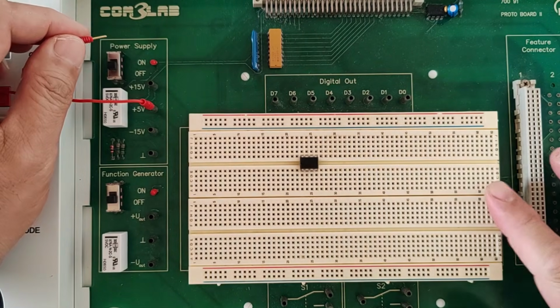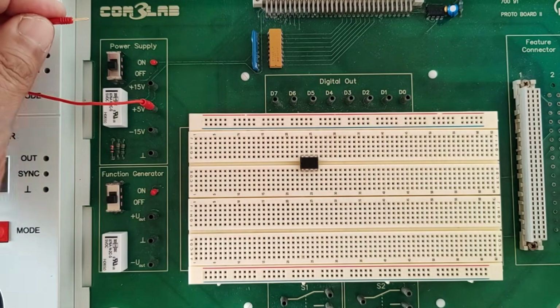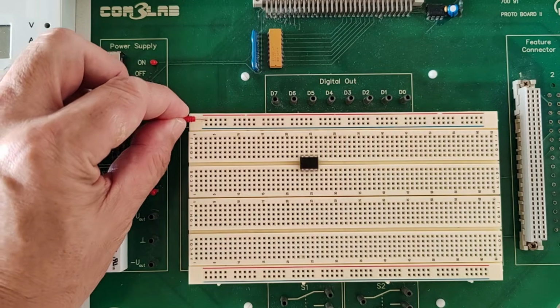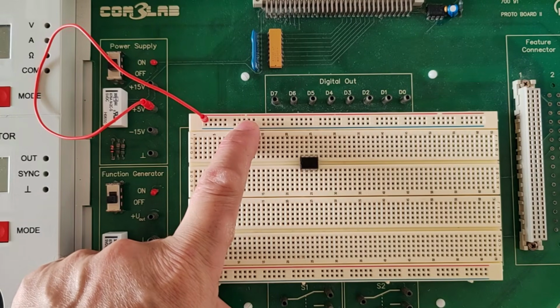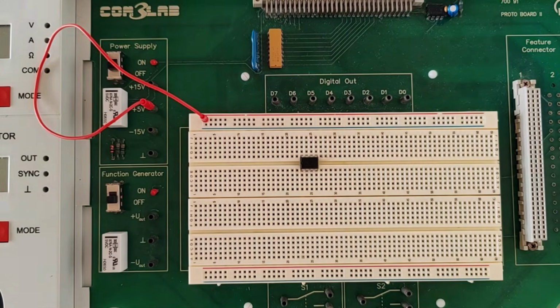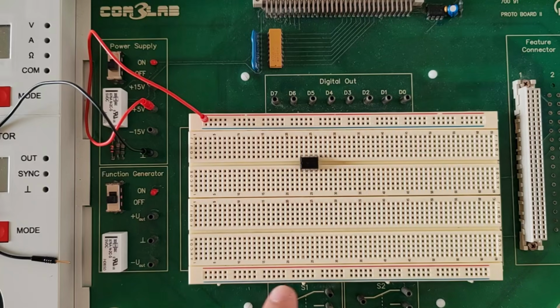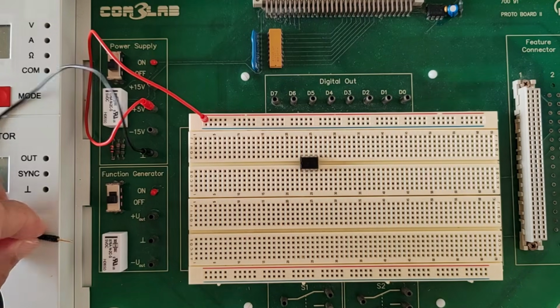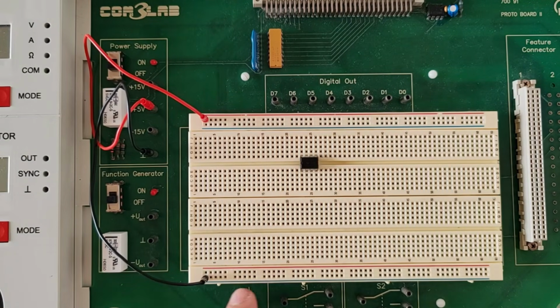And I will establish now here on the breadboard where this 5 volt line will be connected. I'm going to use the top power rail, the red side of the top power rail. So from there, I've established that the top power rail, red side, will be our 5 volts. For the ground, let me connect a second wire to the ground. This time around, I'm going to use the bottom power rail, the blue side. So let me just do that. I'll insert it to the blue side. So here, the bottom blue power rail will be our ground.